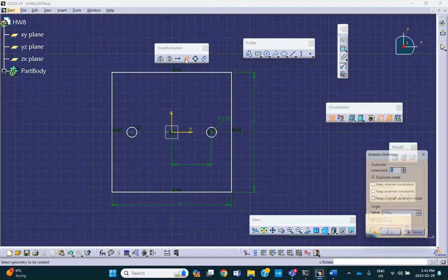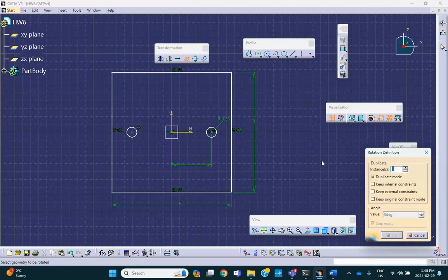Let's try to do this rotation because we have to read this carefully. Select the geometry to be rotated. This guy. And it says then select or click the rotation center, and there's the rotation center. Okay, and then select the point to define the reference line angle. So let me, okay, you see this?